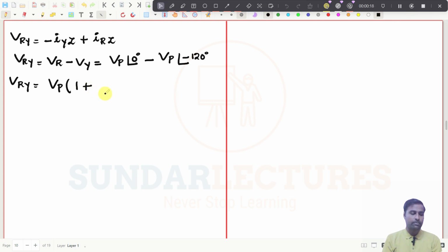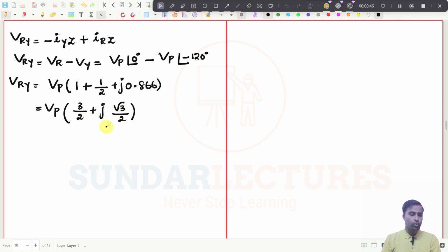Then it will come as plus 1 by 2 plus J 0.866. You just convert and take VP commonly outside, then you will get an expression like this. So this will be equal to VP, and if you take LCM, it will be 3 by 2 plus J root 3 divided by 2, right? Then you take root 3 commonly outside, and it will be like this.